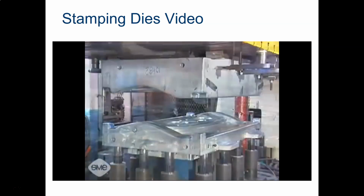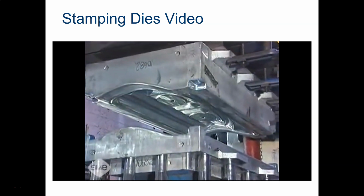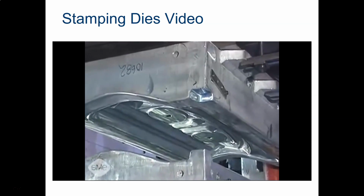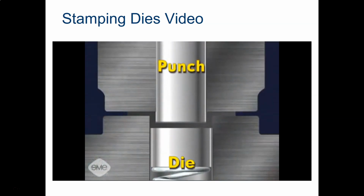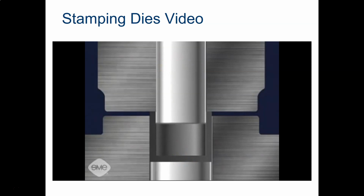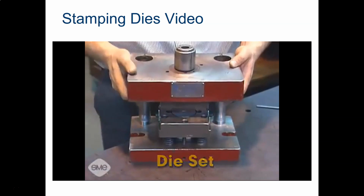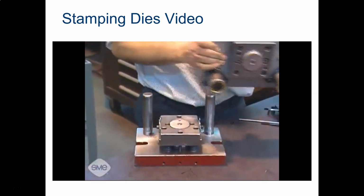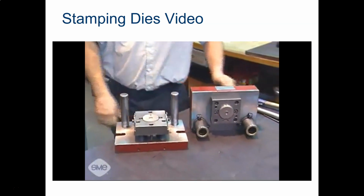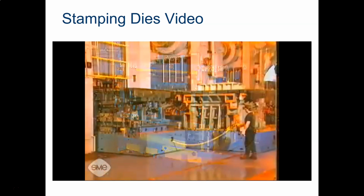As a generic term, it represents the entire press tooling used to cut and form metal. However, the term die can also refer to only the female half of the tool set. The male punch mates with the female die, and working in opposition to each other, they form shapes and punch holes in sheet metal. The term die set refers to the upper and lower die assemblies, which are also called punch and die holders or shoes, as well as other components. Die sets can take many forms, shapes, and sizes.